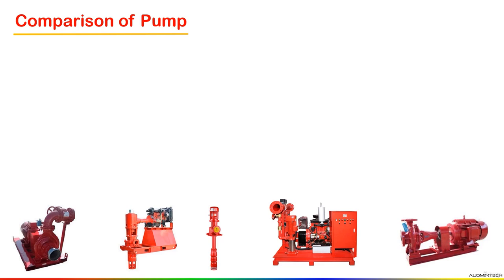That is why we call it a horizontal pump: if your shaft position is horizontal, we have to call it a horizontal centrifugal pump, otherwise a vertical centrifugal pump. And remember, this horizontal centrifugal pump requires more space as compared to a vertical centrifugal pump. And it cannot handle more pressure and temperature of fluid on the suction side, but a vertical centrifugal pump can work efficiently with higher pressure and temperature conditions, okay.